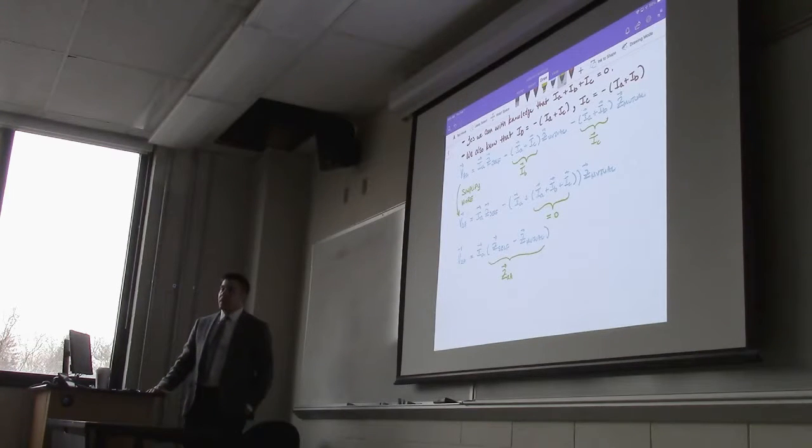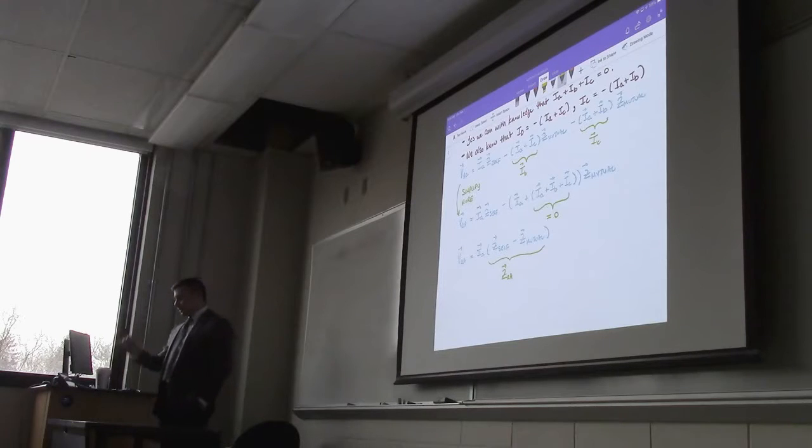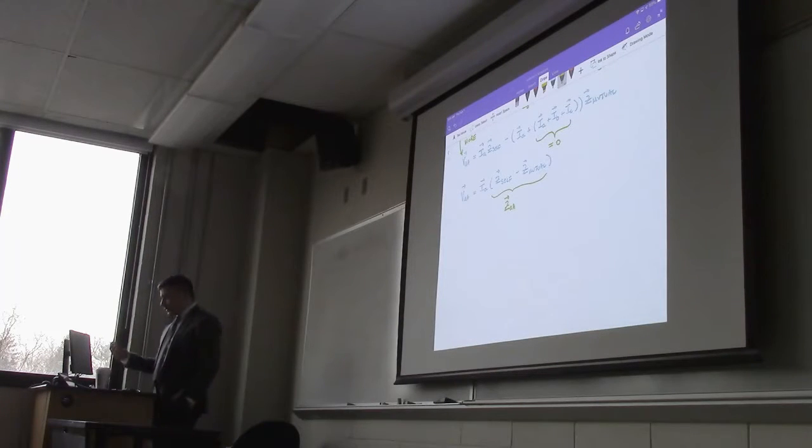They'll either give you the impedance matrix or they'll say the equivalent impedance for phase A is 2 plus J10, and the mutual inductance will be included in there. But you should understand that that value, that J10, represents both the self and the mutual inductance, or impedance. 99% of the time it's that.